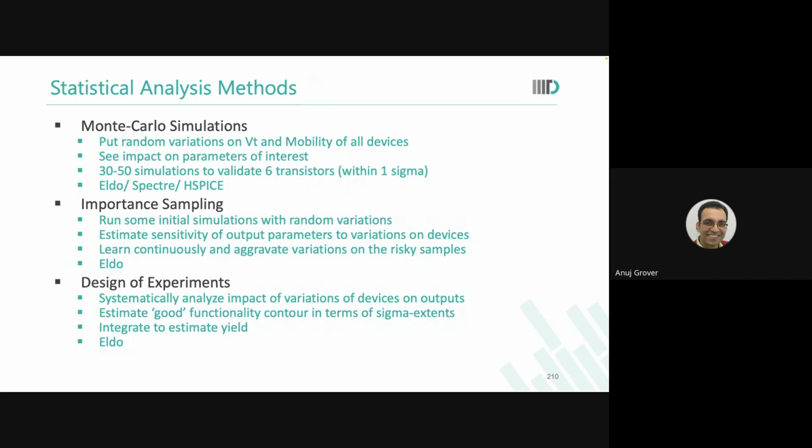So I have first, through a few random simulations, identified the worst case region. And then I have done more and more simulations in that worst case region than in the entire distribution. With the hope, again, hope, that I will now be able to see at least one worst case simulation in my 500 Monte Carlo runs also.